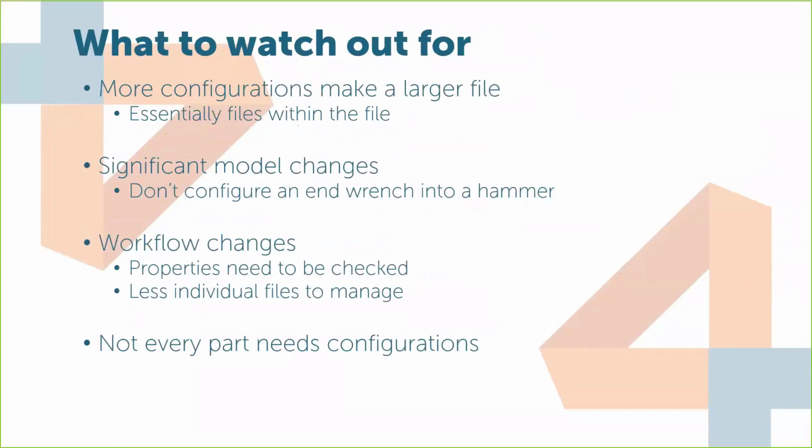Now, a couple of things to watch out for. I mentioned this a few times, but the more configurations you have, because all the data is stored within the single file, the larger that file becomes. You can almost think of it as files within a file. That's not 100% accurate. For example, if you have 15 part files, and they are each 1 megabyte, we add those up, we've got 15 megabytes worth of data. Those are pretty small part files anymore, though. But if I had one part file with 15 configurations to represent those 15 individual files, if it was a family of parts, it wouldn't necessarily be exactly the same as adding those file sizes up, but it's going to be close to it. So that's something to think about. The more configurations you have, the larger the file is. If you have parts with hundreds of configurations, that could be a very, very large part file, and you have to deal with it that way.